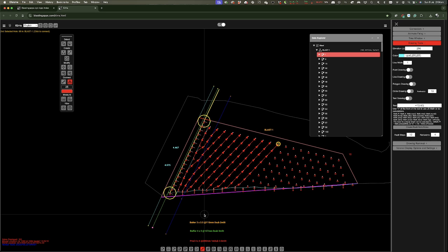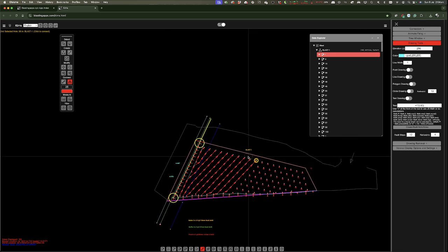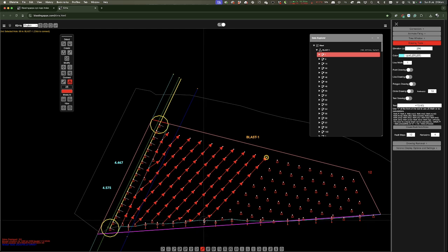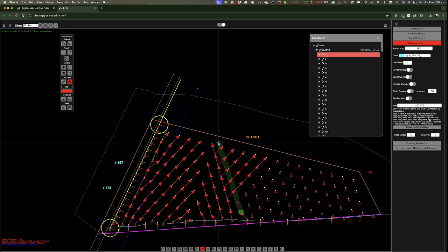But what you can do with this is that if you've done the wrong thing and you're going, oh, I don't want to fire from here and advance it all the way back, I want to flip it. Well, you don't have to delete anything. That's the key. You just start tying in to where you want and it will overwrite those connections. Each hole can only have one arrowhead, but a hole can have many tails. Yeah, so you just keep clicking away, right?